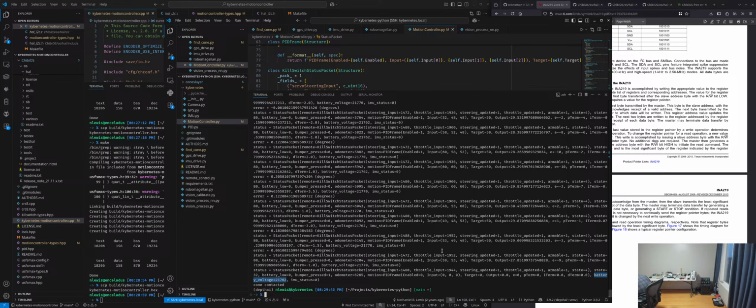Alright. So, the voltage, if I measure it, I can actually get good contact on my probes. Okay, DC voltage is at 10.93 volts on the logic supply.